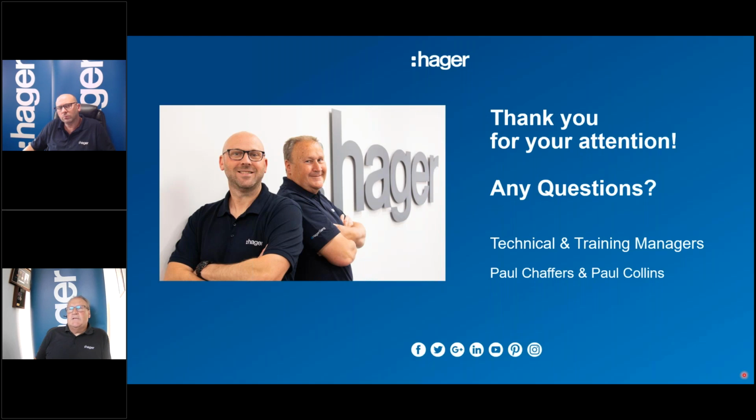I'll take that one. I think I understand that. So when you've got RCDs in series, the one upstream needs to be at least as good as the one downstream. Can you remember that hierarchy? There's AC, A, F, B. Obviously they get better as you go down that line. So you wouldn't have a worse one upstream from a better one as such. You should not have an AC upstream from an A. There are times when you can, actually, but this is a general requirement. AC shouldn't be upstream from an A. So if there were all A's, that's fine.